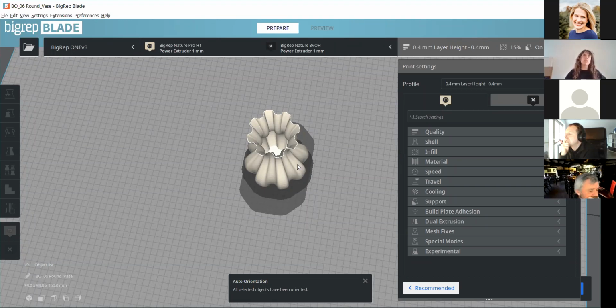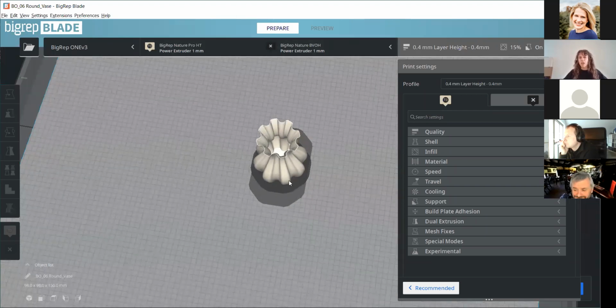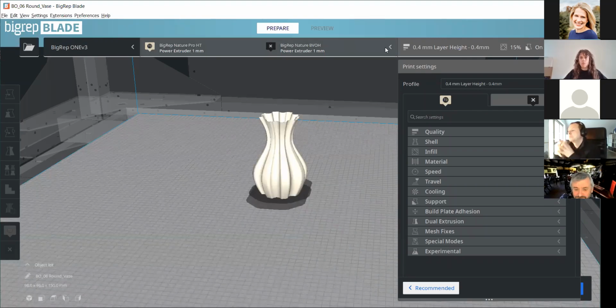Essentially, what it means is it's nonstop printing. So it can print a bottom surface and one loop on the outside nonstop. So it's actually technically the most optimized option for FDM because it's extremely fast, no retractions, and no seam. But obviously it works, you know, 5% of the time when you're printing for FDM. But for a part like this, it would work.